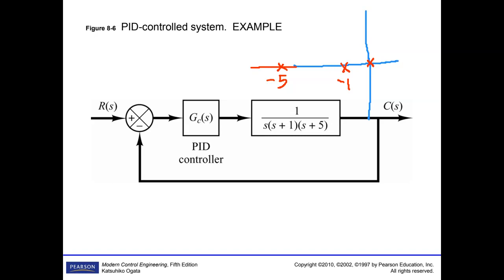The root locus curve. When you increase the value of k, in order to obtain this value for this point, if you measure k, if you obtain the Kcr, which we obtained, it was 30, remember that. We used the Routh-Hurwitz method. As long as you obtain that one, you already obtain Kcr, and then you wrote the equations.